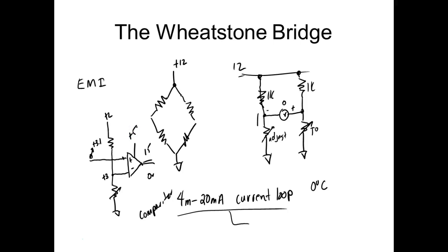So these are sensors where you can actually adjust what we call the threshold voltage. There's a lot of sensors where you can determine where it trips between outputting a voltage or not outputting a voltage. These sensors will have a little screw setting. Usually they're recessed, so you have to get a little screwdriver to turn them. They usually don't put knobs out there, and why is that? Because people will turn them. So they usually make them a little hard to do.